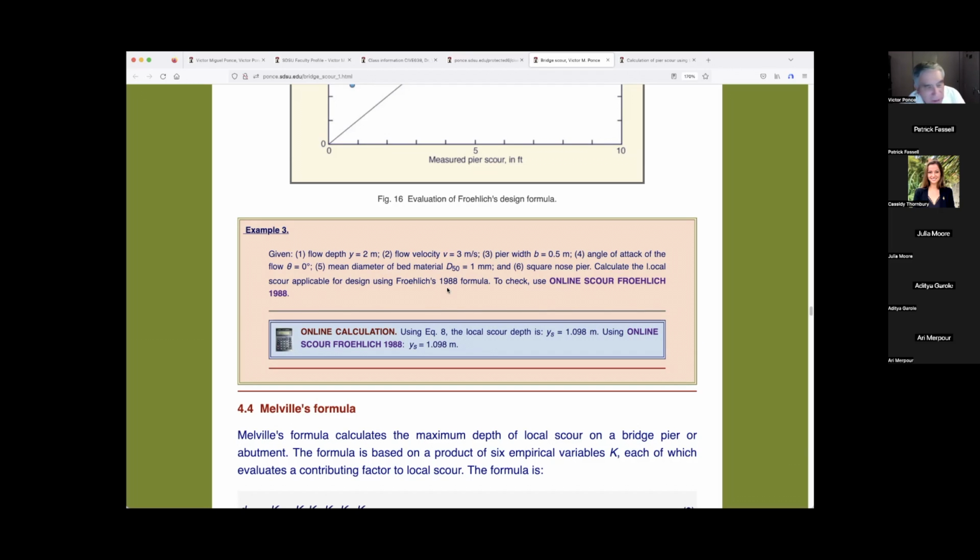Why is that? I think it merits that we discuss that at this point. In structural engineering, the typical practice requires a factor of safety because there's a lot of uncertainties. And there's 2 factors of safety, one on the load and one on the material. So if the material has X strength, you would put in there the load should be 1/3 of that, because typically the factor of safety is 3, and the load the same. So in typical structural design, there's a factor of safety of 3 on the material and 3 on the load. So by the time you multiply both, you get a factor of safety of 9. And that's the reason why buildings don't fall apart or fall under their own weight. Do buildings fail? The answer is yes.